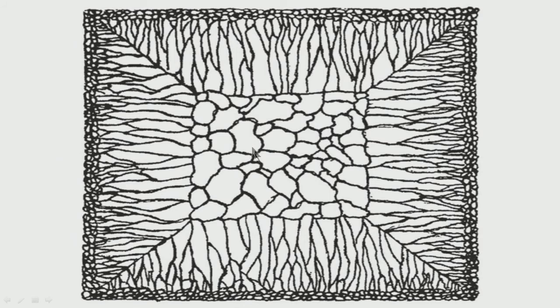If you have this equiax zone, then what happens? The segregation and the cast abnormality at the center gets distributed. If you have high superheat, the columnar zone extends to the center, and the center becomes highly segregated, with a high amount of solidification shrinkage at the center portion. That means we do not want high central segregation, we do not want high central porosities in any cast structure, because that is a defect, we do not want that.